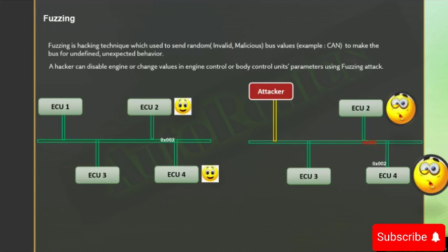Now, via your OBD, if you are connecting with any CAN analyzers or a mechanism which can send a message in OBD with the same engine message arbitration ID, if you simulate a value of 0, your message also will be ingested in the vehicle, and at the same time the engine cranked information also will be sent in the same message to EPS. But the EPS ECU will be confused, meaning both will have the same arbitration ID, but one message says that the engine is running, the RPM is 700, but the other message says that the engine RPM is 0. It will be completely confused.